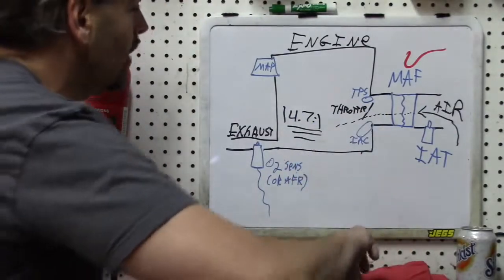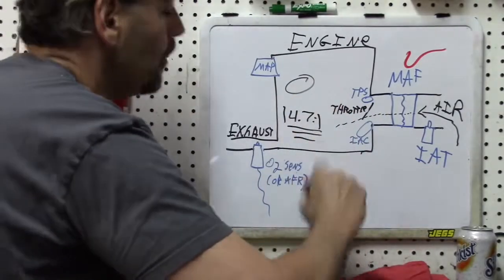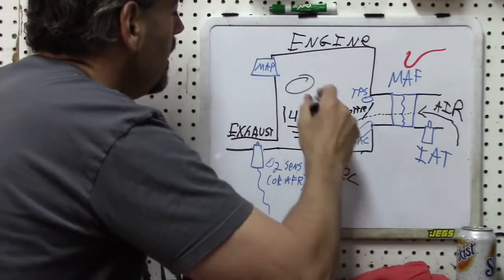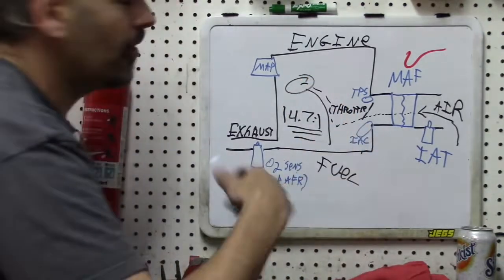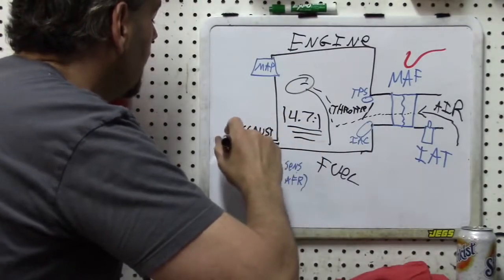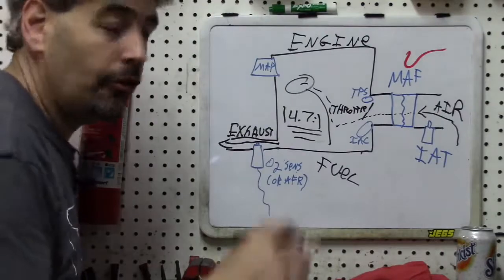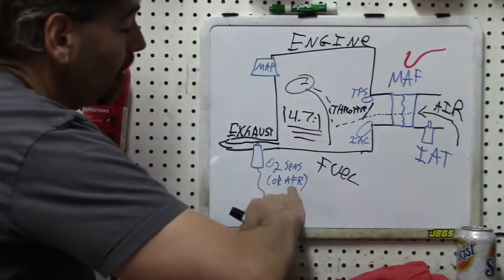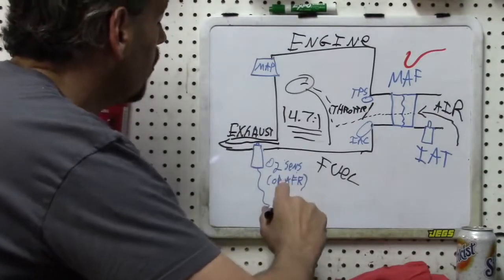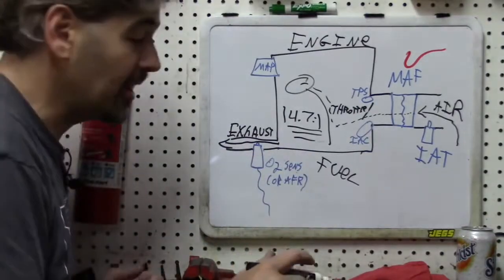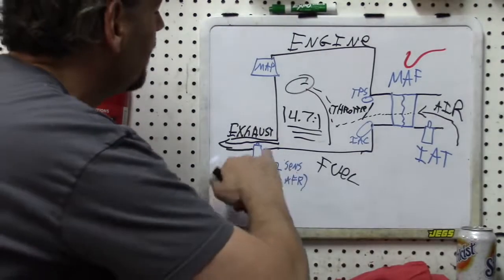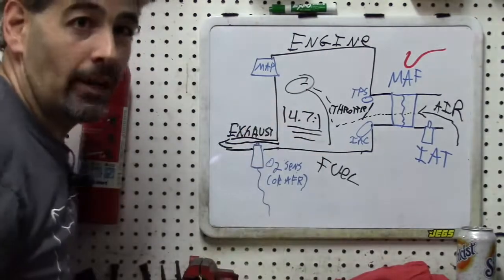Of course, you've got your cylinder, your fuel, and the air mix in the cylinder and combust, and of course that exhaust is validated by the O2 sensor, or in some cases the air-fuel ratio sensor in newer cars, to look at the amount of oxygen present in the exhaust and also hydrocarbon and determine if this mixture went accordingly.